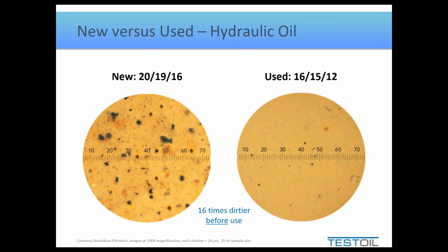So this is why it's so heavily stressed in many industries to pre-filter our oils, whether we pre-filter them as we take delivery of them, when in storage, as we dispense them, or to at least at the minimum expect that the particle counts will increase after an oil has been put into a system before the system gets a chance to circulate it and clean it back up. So hopefully ISO codes are making a bit more sense to you now. You have an idea as to how to read the codes relative one to the next, but also a visual on what that might look like in terms of how much dirt, at least per drum. So getting back to step 1, we need to understand new oil is not clean oil.